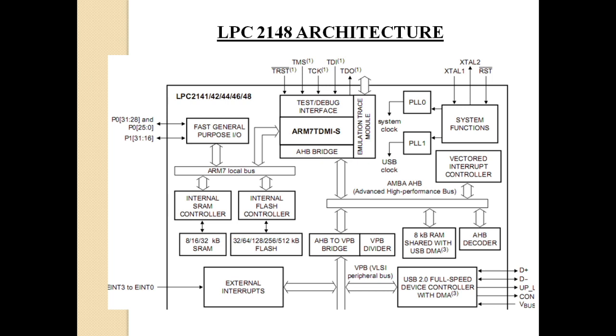So here in the case of a microcontroller or microprocessor, how will you generate a clock? You are using a certain peripheral known as a crystal oscillator. It is a small component. That component can generate an accurate clock, right? So that crystal oscillator will be connected across this Xtal1 and Xtal2. So that is also a passive component. It cannot generate its own clock. So what does it do?